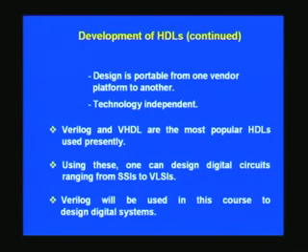And two most popular HDLs used currently are Verilog and VHDL. This is in the realms of digital circuit design, and recently Cadence has come with mixed analog and digital circuit design using Verilog, and they call it Verilog-AMS, and you can implement A to D converter, D to A converter, and PLLs and the rest of analog circuits, and you can mix it with the digital circuit as such.